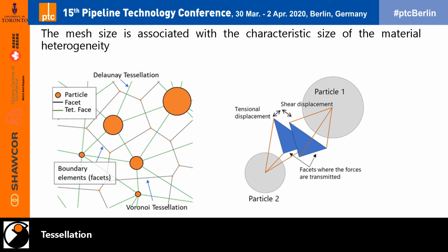A Voronoi-like mesh is built on top of the Delaunay tessellation of the particle locations. Here, a 2D model is shown. On the left, the black lines show the interface boundary, where one element is aggregate bonded with mortar, and the black line represents the interface between them. The interfaces are called facets. On the right, facets are shown for a 3D model that act as interface elements. In LDPM, failure can occur only at interfaces.